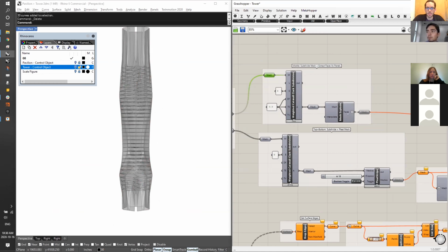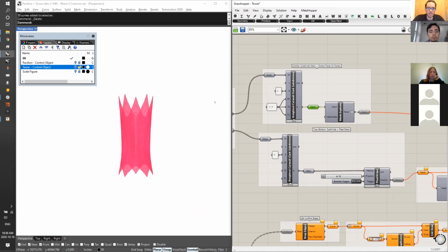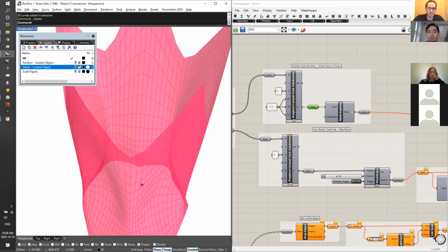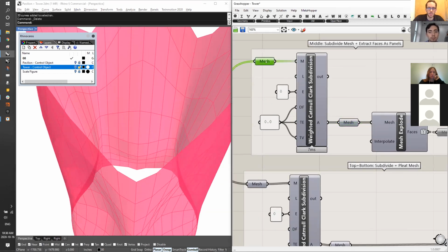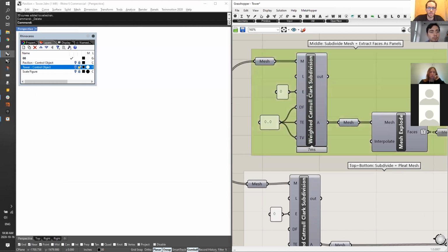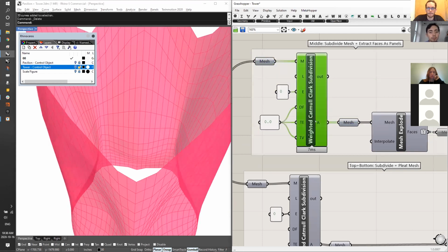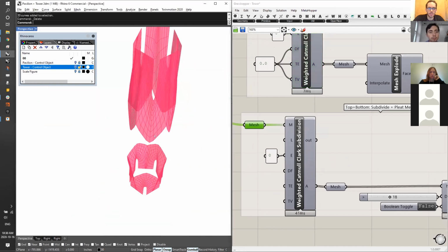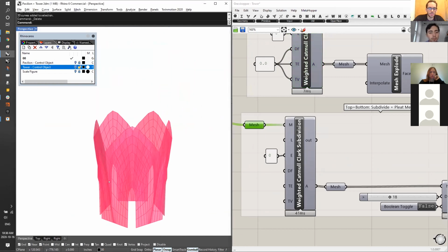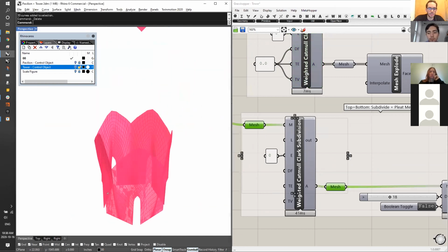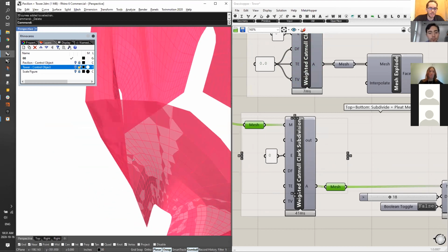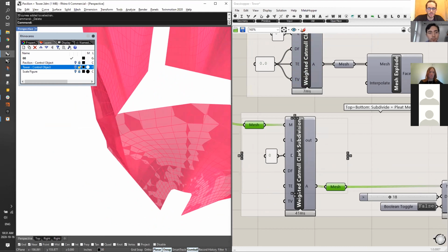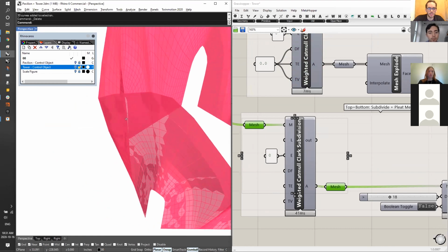So the middle gets subdivided and it remains relatively flat with the edge weights of 0, 0, 0. So in other words, we're just adding more panels proportionally. And in the other one, we're subdividing it, but we're not merely adding more panels. We're actually smoothing it to some degree, so that we're smoothing out any kinks around it, except any edge of it, so any edge conditions must stay locked in place.